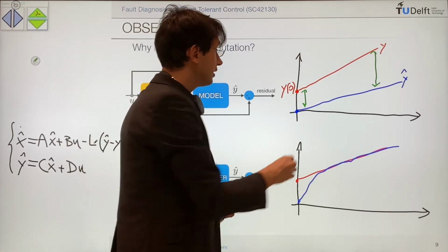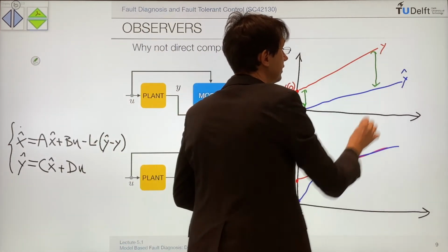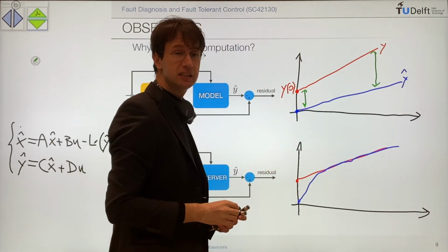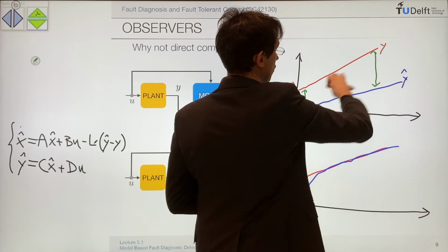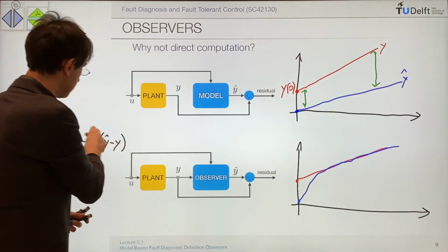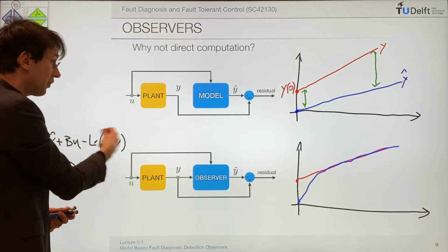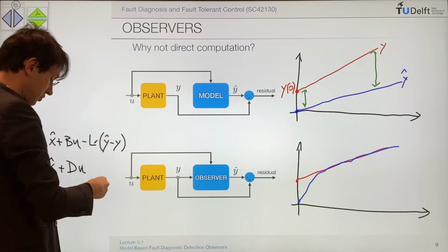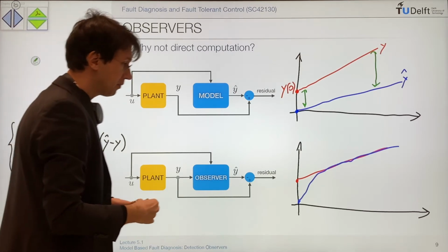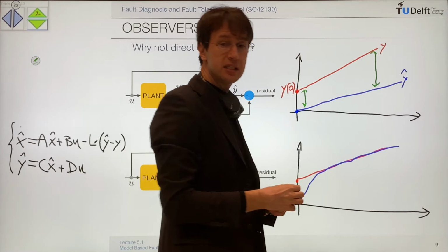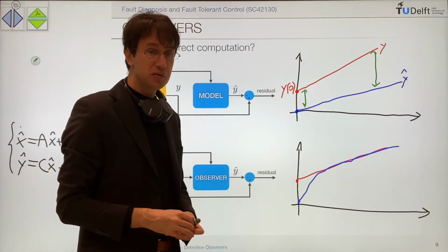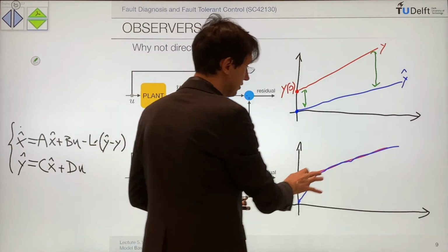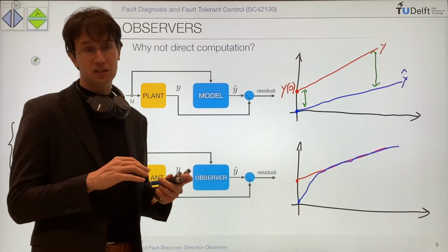But this long-term drift is something that is corrected, because this long-term drift is basically some low-frequency behavior, and is not going to be filtered by this. It is going through that, and so it is used to correct the estimation. And so this is the reason why we need observers, because observers will track your system well under suitable assumptions.